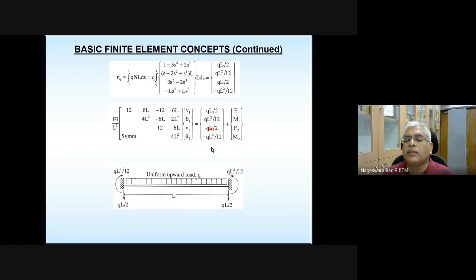Please note that this vector is on the right side. So it is going to be similar to the given distributed load. What are the equivalent forces for the given distributed load? What is the equivalent force at node 1? Equivalent moment at node 1? Equivalent force at node 2? Equivalent moment at node 2.